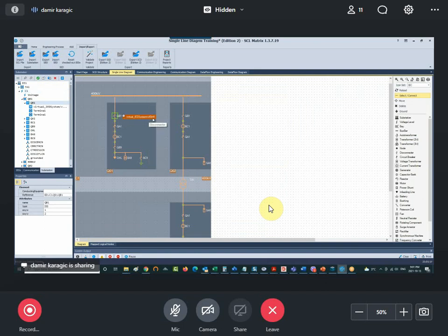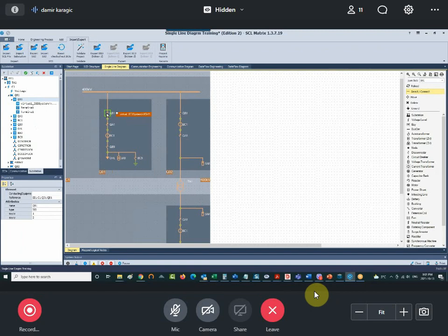It has to be functionality that is described with logical node X switch, and it has to be data objects and data attributes as defined by this virtual IED. Now you can also obviously import vendor IEDs and use them, but the only difference is here we are vendor neutral, while in bringing vendor type ICD files, we would be asking, okay, we want vendor specific IEDs to be used.